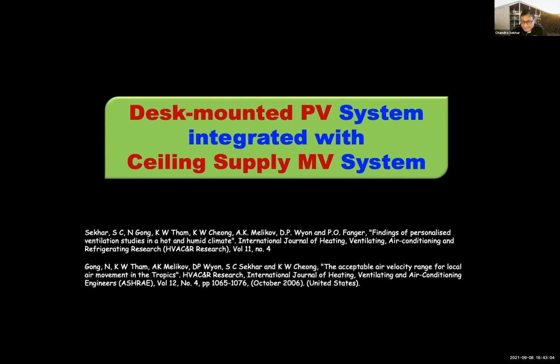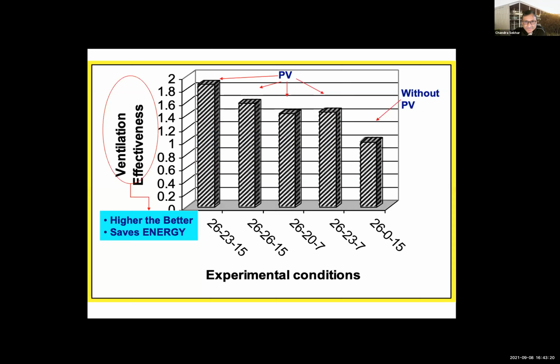We tried several different configurations. I'm just going to share with you one of them, maybe a couple of them here. What we call a desk-mounted personalized ventilation system. PV here is personalized ventilation, not the other PV that most of us might be familiar with. Integrating that with the conventional ceiling supply mixing ventilation system.